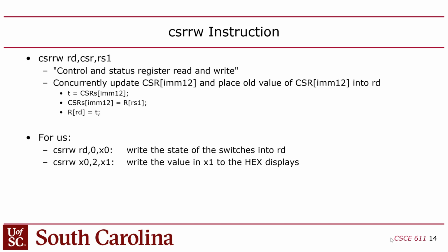Now, the only issue here is if you actually use these in RARS, I think it'll give you an error. Charles used to have a modified version of RARS that got around that, but I don't know what happened to that. But it's not a big deal, because when you're testing your code in RARS, you can just replace one of these with a load immediate, right? And you can just comment this one out, right? But when you deploy this on the FPGA board, you're going to put those back in.